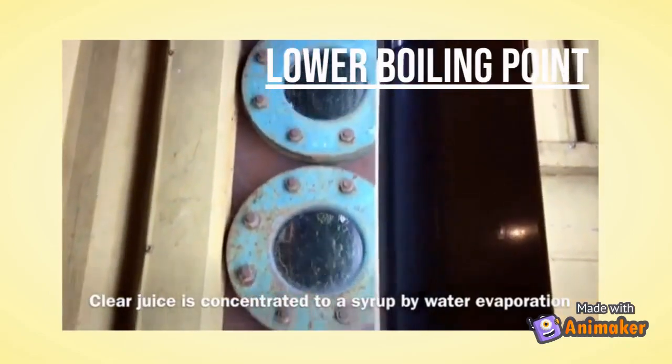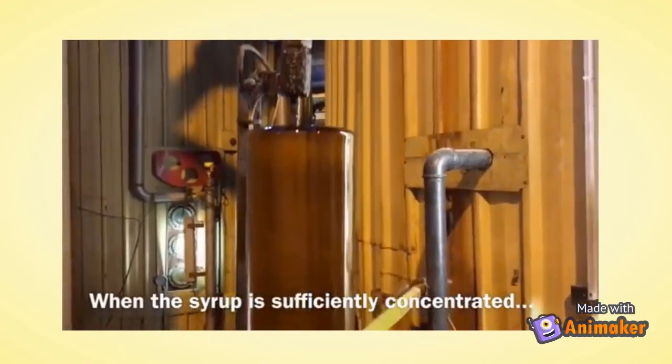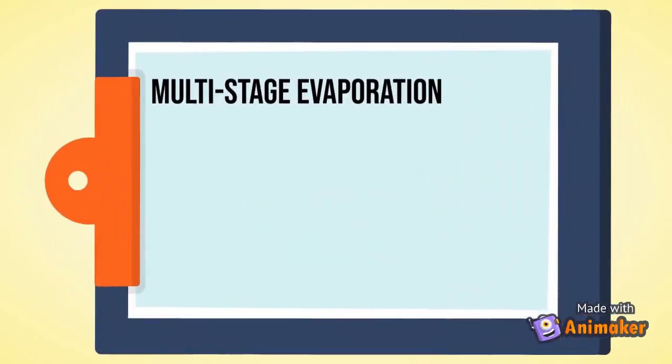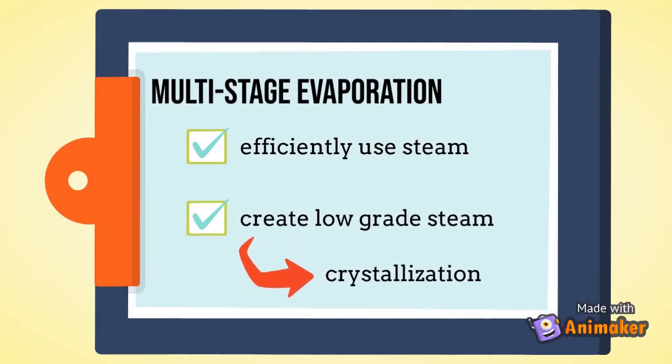In this process, inorganic salts such as silicates and oxalates are removed and a syrup with a 50 to 65% concentration is obtained. Note that multi-stage evaporation is used to utilize steam efficiently and to create a low-grade steam that can be used to drive the crystallization process.